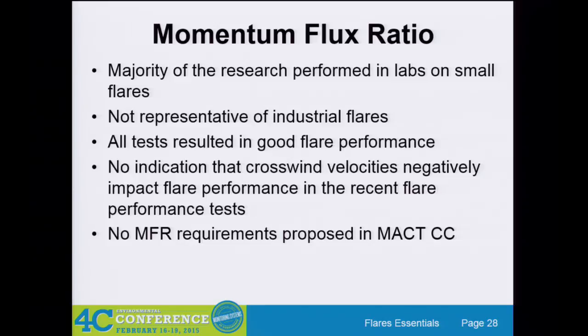Because when we've seen it put into practice, the amount of gas that you have to add to overcome some of these MFR requirements is a huge quantity. We're talking probably on the order of $1 million a year. So that is not an insignificant amount of cash. And they kind of commented that since we don't think this is an issue, we don't want to make you put a bunch of extra natural gas into your flare to overcome something that isn't important anyway. We don't want to increase emissions, we want to decrease emissions.